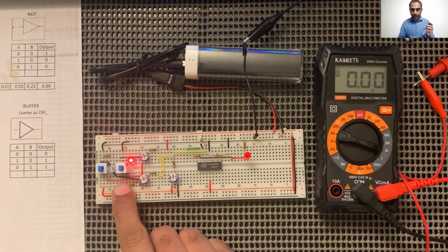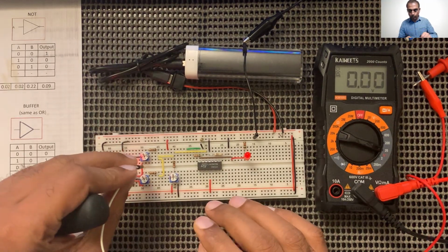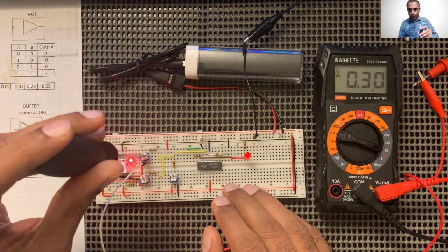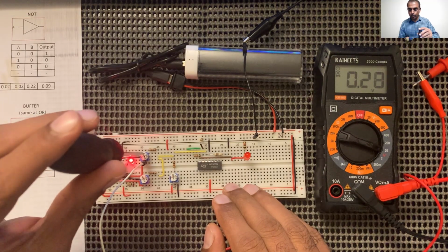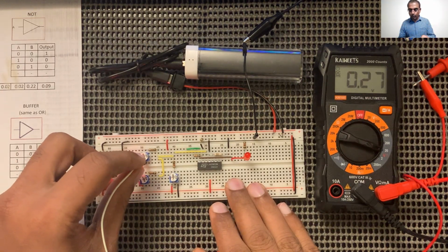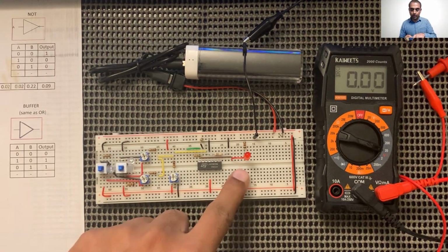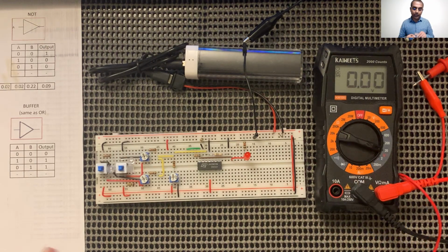You may see that when I switch on input B, there's a slight glow on the LED. That is because the voltage at potentiometer B is at 0.3. If I tune it a little bit to the right and set it to 0.28, now you see that LED is no more glowing. Maybe you may not be able to see on the video, but through this angle from here, I could see that little bit of a glow on this output LED. Okay, now this perceptron is configured to behave like an AND gate.